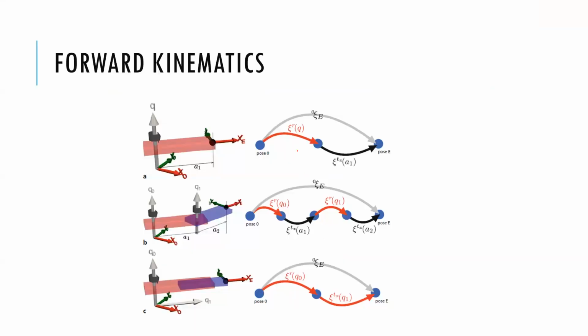All right, so this is a better graph of what I did before here. This is just a rotation of a single thing here. You can see it's the rotation component, and then I added a translation component. And we already talked about pose graph, so that's going to be equivalent from the base to the end effector. Here is a 2R system, 2 degrees of freedom. It rotates here and rotates here. I rotate it to get this aligned, and then I translate it. And then I rotate it to get this aligned and a translation. So a rotation, translation, rotation, translation is a 4.